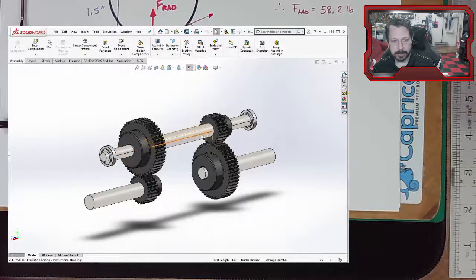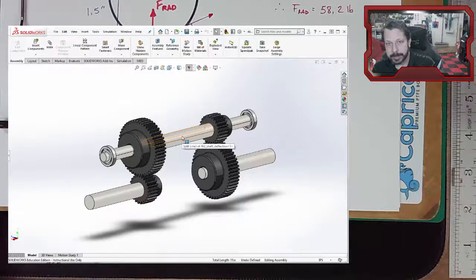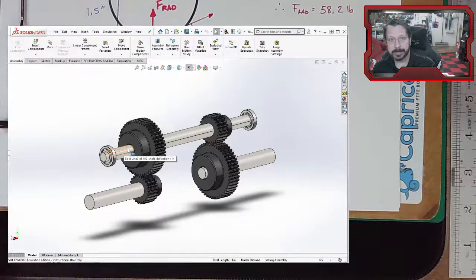A lot of times the deflection is going to be difficult to do by hand. You can get a rough estimate by taking the thinner diameter as the whole size of the shaft. If it passes that way, then making it bigger for the steps and shoulders is not going to make it fail. It's going to make it fine. So if you had to do it by hand, you could use a constant-diameter shaft at the thin part and see if that passes the deflection.